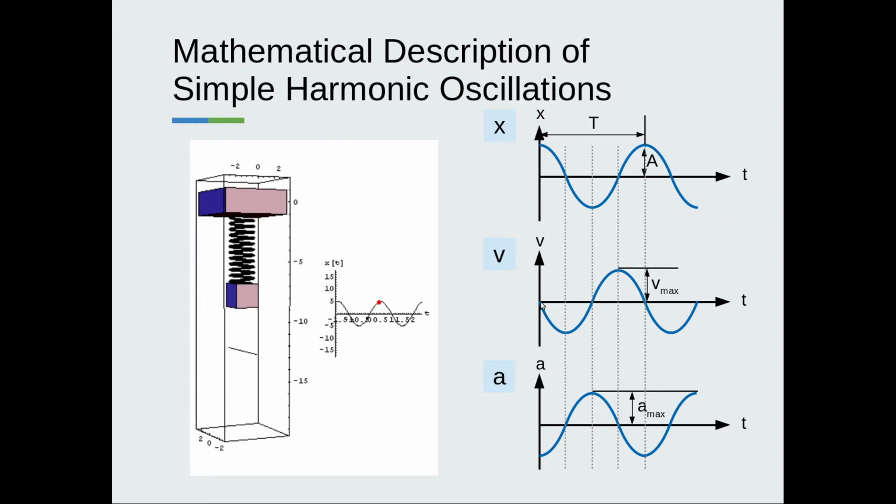and for the velocity it started from 0, and the velocity is changing that way. And for the acceleration, then you can see that this is how it started and how it goes on. So actually you can see that they are the sine or cosine function with the same period, or you can say they are having the same frequency, but they have phase shift.